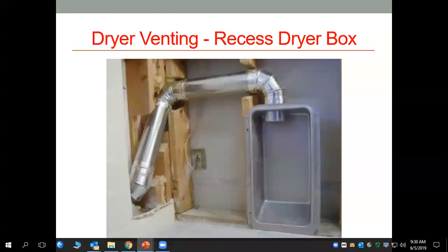But my last one is you never know what's behind the wall. So if you see it after it's sheetrocked and you didn't see that, you would think that that was okay. But you see what they did to the framing and to just the way it's ducted, mostly the framing, how poor that is and how that'll affect the structure of the actual wall and of that room and maybe the house.